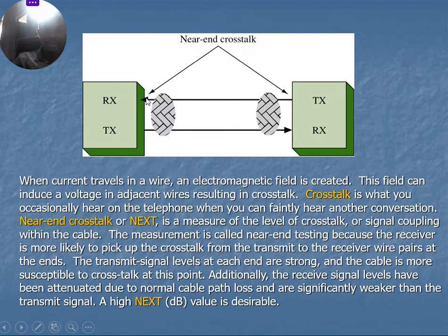And at the other end, the receiving end, there's also crosstalk happening. Now this is full duplex mode. This device also transmits and this device also receives. This crosstalk happening at the near end to the device on this part and also on this part is called near end crosstalk. Is that okay?